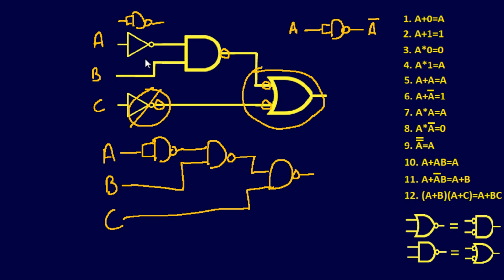So now let's go ahead and check our answer just to see if we're correct. So I have A0, B right there, go into an AND gate. I'm not taking into account these bubbles right now, I'm just checking our original equation. So it's A0 times B, and then right down here we have C0, and this is going to an OR, so it's A0 times B or C0. That seems pretty simple. So let's check this one down here and see if it actually has the same output.